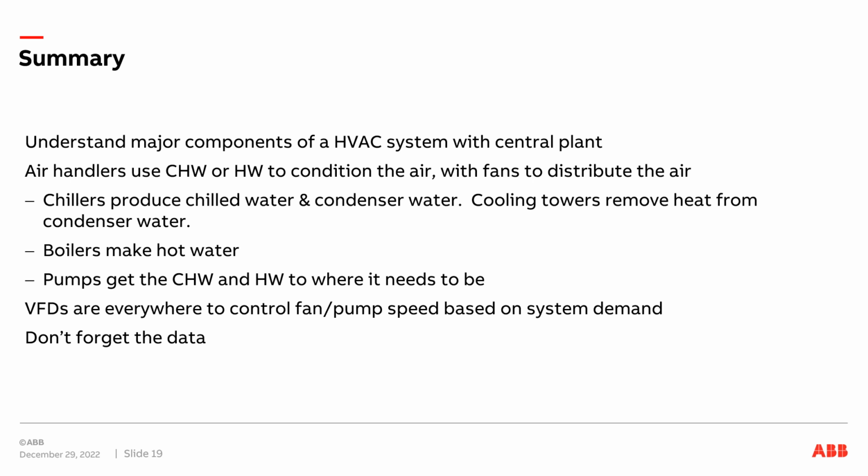As a side effect of making something cold, something else gets warm. That's called your condenser water. To get some of the heat out of the condenser water to continue that refrigeration loop, you have cooling towers involved. Our system happened to be unique where we use some of that condenser water and piped it into our hot water system during the summer, so we can get basically free hot water for our HVAC system. If you don't have that, or come wintertime and your chillers aren't running, you got your boilers that make hot water. And again, it's all getting moved throughout the building with your pumps.